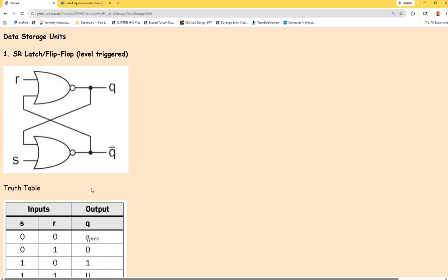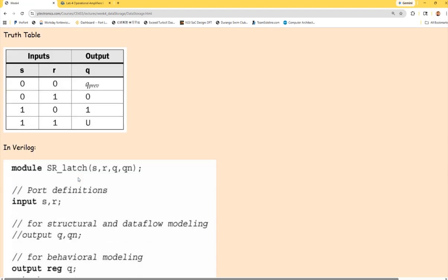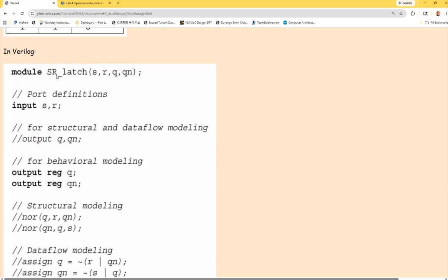But for here, when you model it with the Verilog, everything becomes simple. So you just look at the truth table and describe it. So see here, SR latch, SRQQN. It's from the textbook. You can see behavioral modeling, always at S or R, depending on which changes. It's a sensitivity list. Because the latch doesn't have a clock, right? So whenever S or R changes, it updates the output. So it's giving a 10 or 01 to the output, to Q and Q naught.